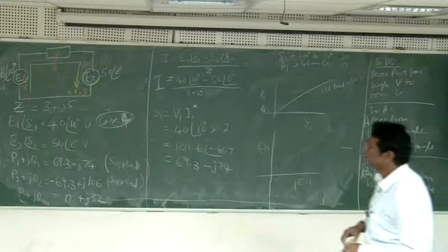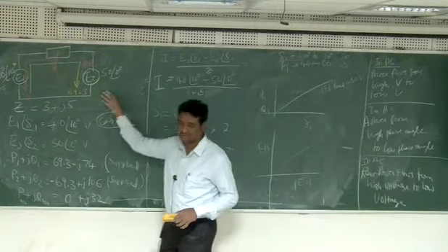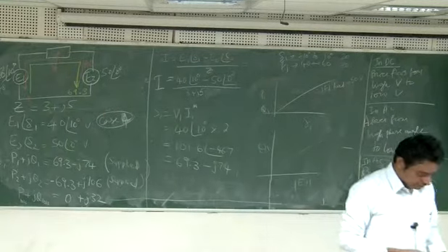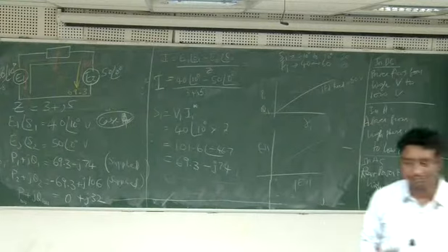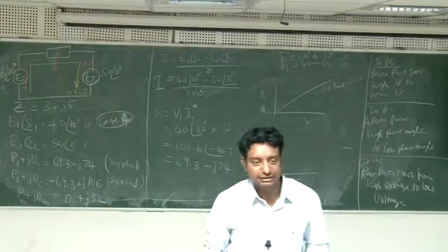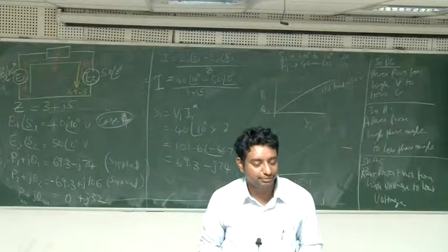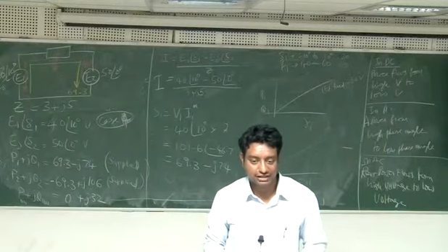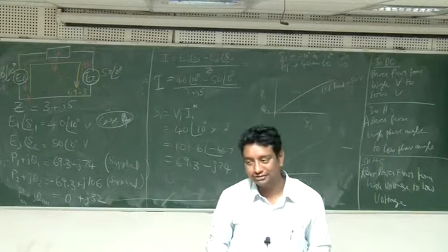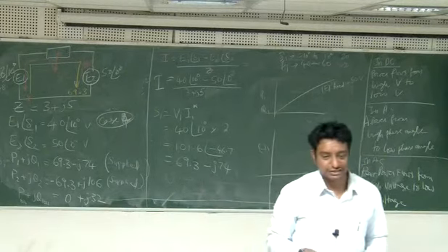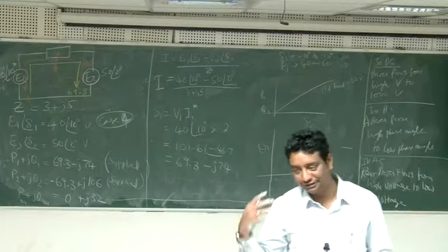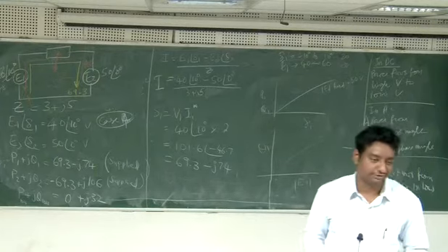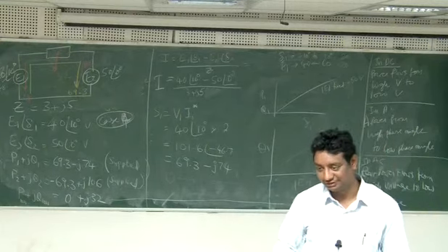Okay, so how do we calculate cost in the case of an AC source? Reactive power does not require any fuel to be burnt. So strictly speaking, the cost of an AC power generator is mainly a question of how much active power it is generating. However, the reactive power will have some kind of fixed cost associated with it, because the design of the machine has to provide some reactive power range.